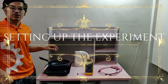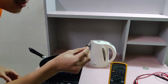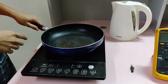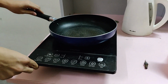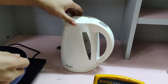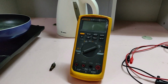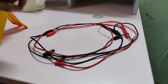So these are the materials that we use in our experiment. The first is the sensor itself, the coolant temperature sensor. Next is a set, which requires an induction cooker and a pan, which we use to supply heat and to manipulate the temperature in this experiment. Next is water, which we use and act as a coolant, and the multimeter, which we use to display the resistance value at certain temperatures, and four sets of connecting wires.